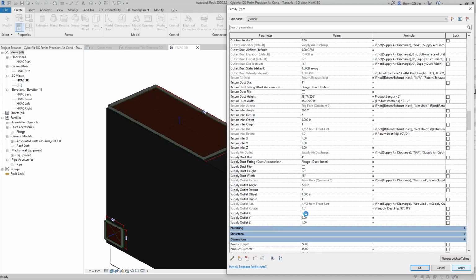So really, when you're dealing with the connector, there's a few things you care about. You care about where you're holding on the connector, what control point you're dimensioning to. You care where you're dimensioning from on the face. You care, of course, about the dimensions of it. And then you care about its position. You're either going to control the X and Z, or X and Y, or Y and Z. It's one of those. It's any of those individual connectors here.